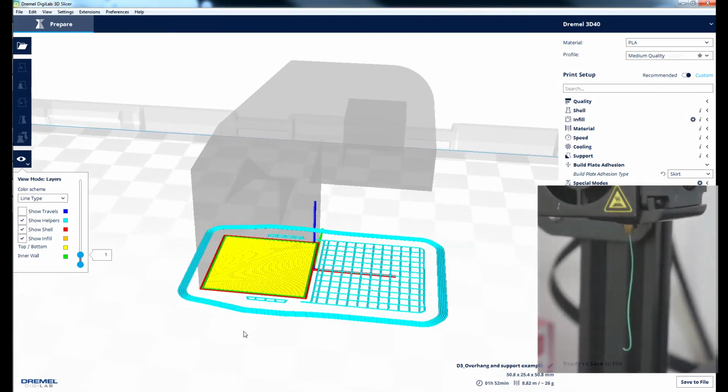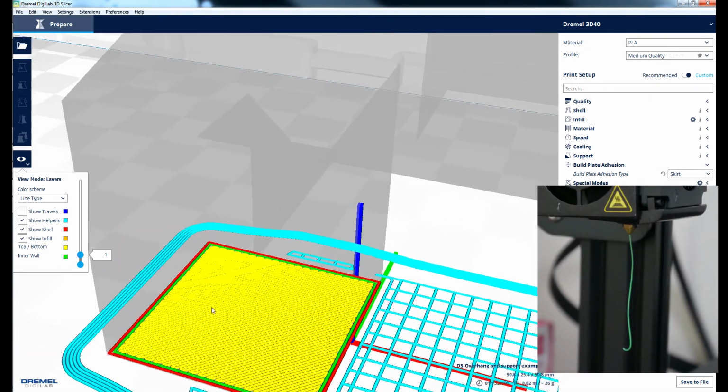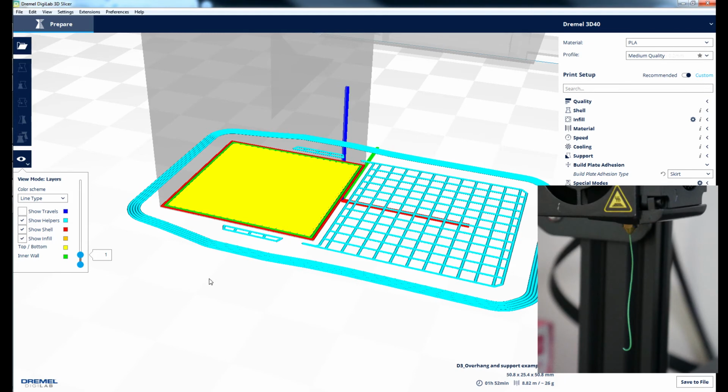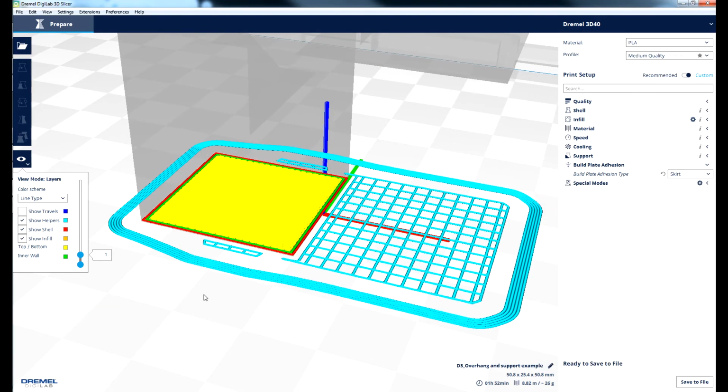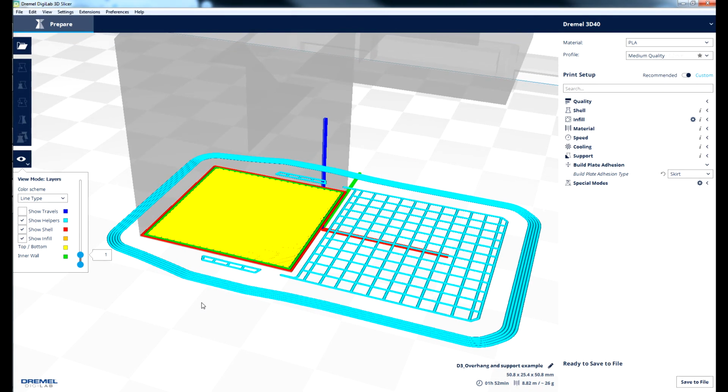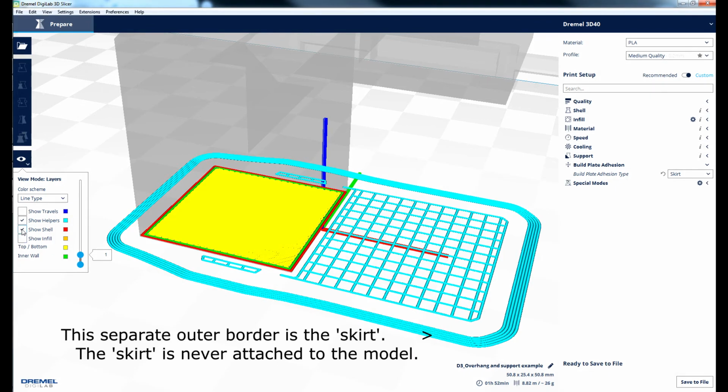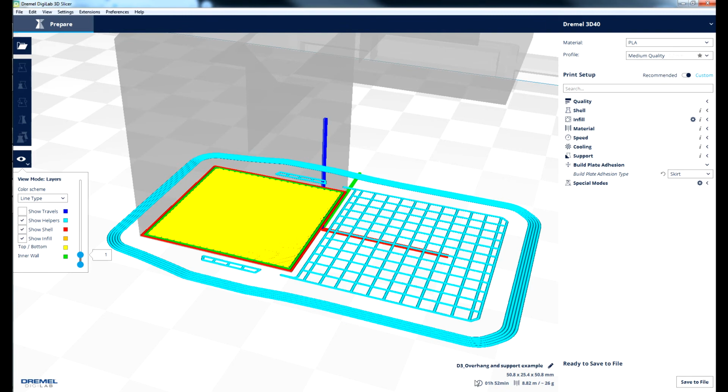When the nozzle heats up prior to a print, sometimes gravity can pull filament out of the hot end, creating a void of filament. If you start your model with this absence of filament, your first layer will contain inconsistencies or worse, fail to stick. Watching the skirt layer print is also a good identifier of your printer's basic configurations. Some telltale signs of extruder blockage, unlevel bed, or nozzle height problems are shown in the skirt layer.